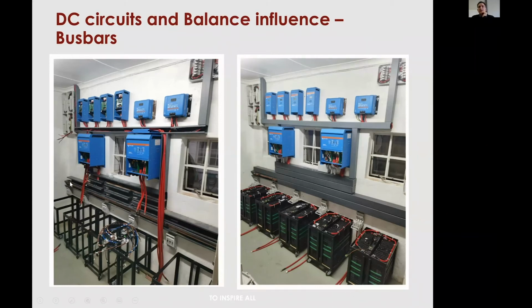And then he has another double set of copper bars here for the batteries, and that's his storage bus bar. When he does that, you can see all of his DC cabling is suddenly reduced from 2 meters, which was in the other picture, to less than a meter.